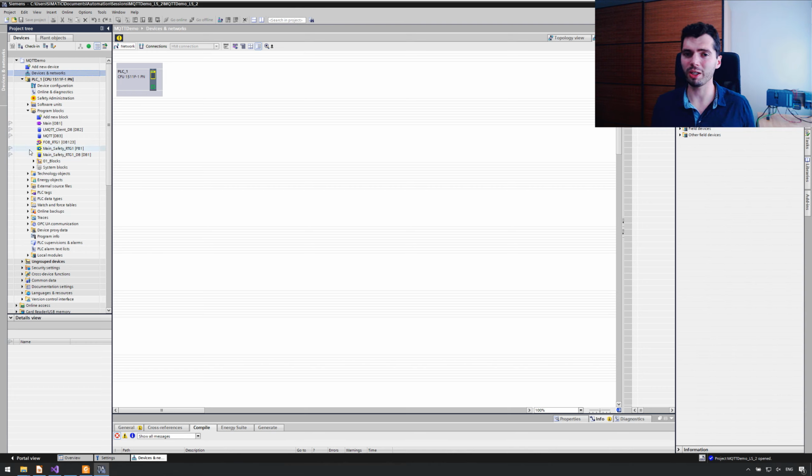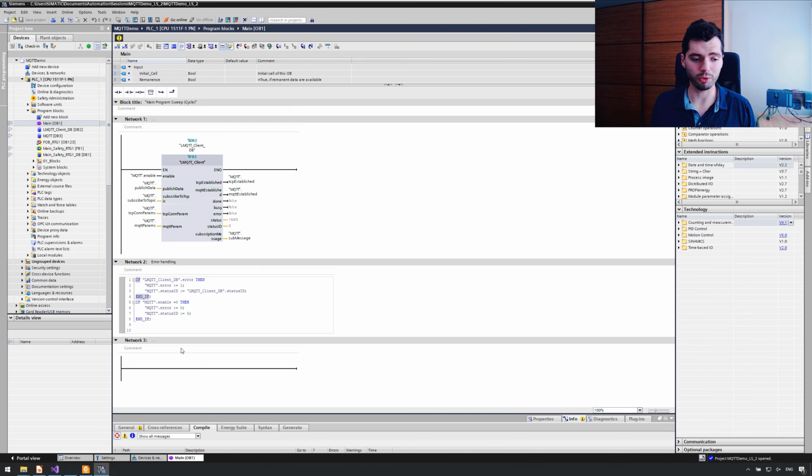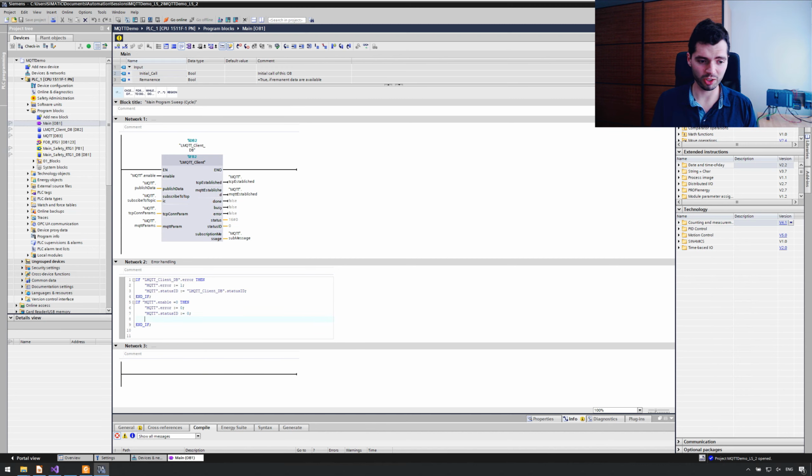And an empty flag means that this thing here is at the same state as it is on the project server. So it's all good. And as soon as I start making some modifications, maybe I modify main. So I go to my main block. Remember, this is my MQTT client. I add something here. Let's say I make a change. Just add a comment. It might be a much bigger change, but let's say it's just a simple change here